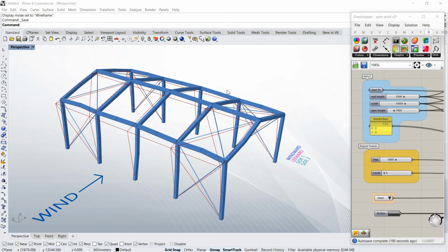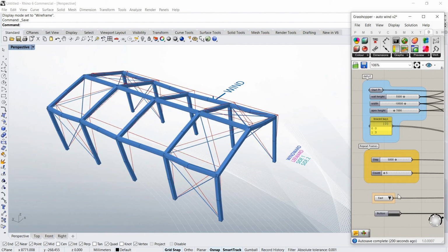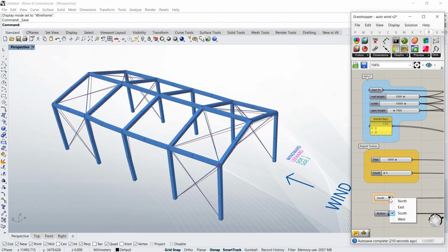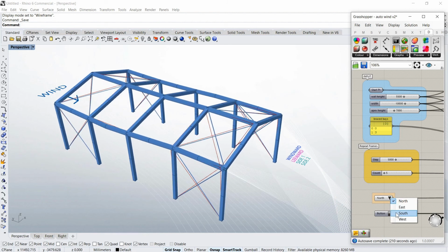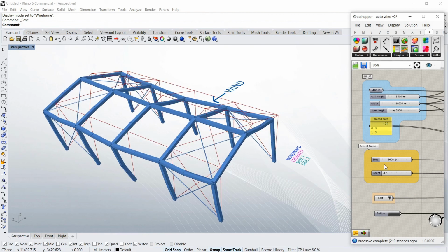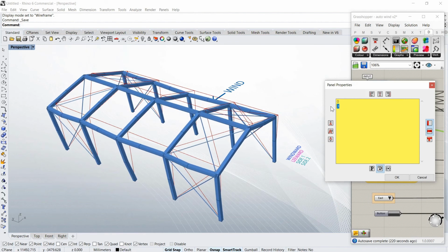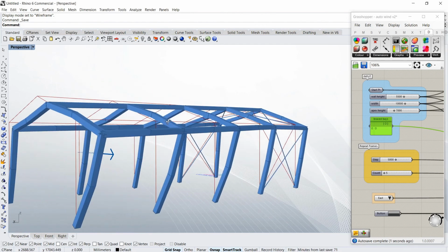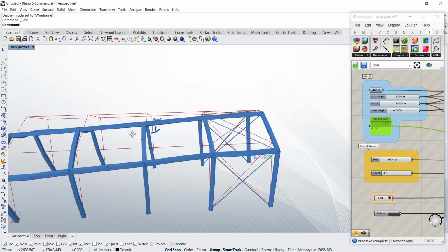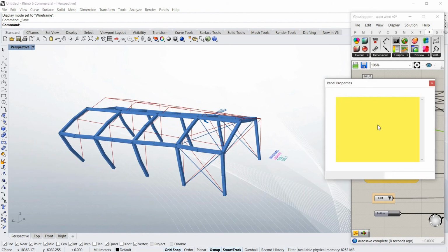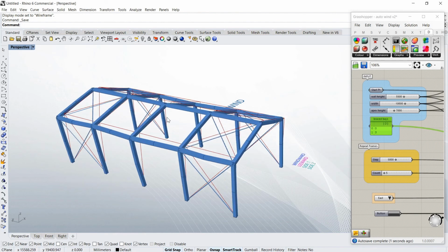And lastly, now we've calculated the forces on the members based on the automatic wind load zones, we can have a look how it's going to behave in a physics model. And of course all this is parametric, so if we deleted one of these braced bays, we can see it deflects quite a lot more without that restraint. That stiffens it up a fair bit.